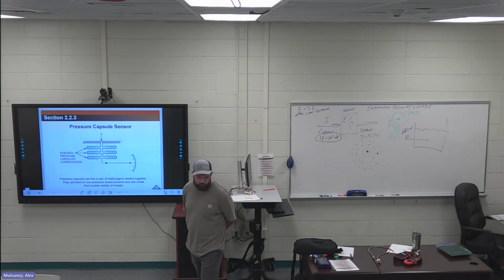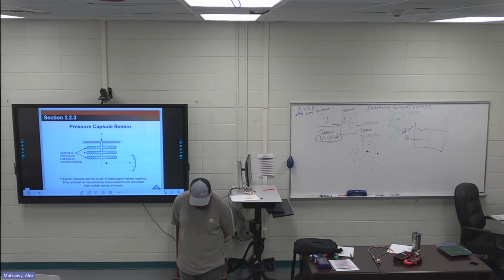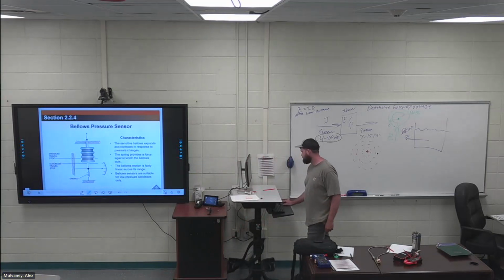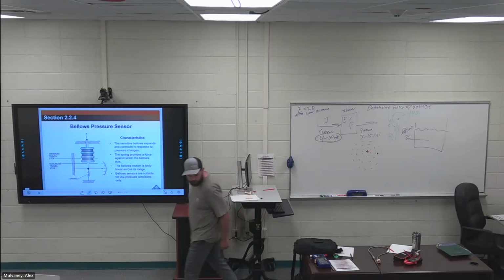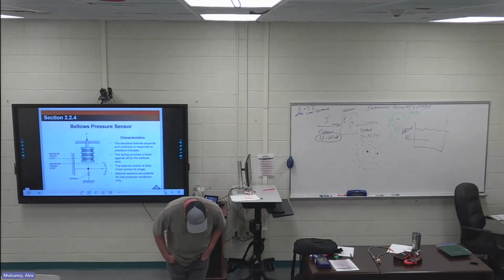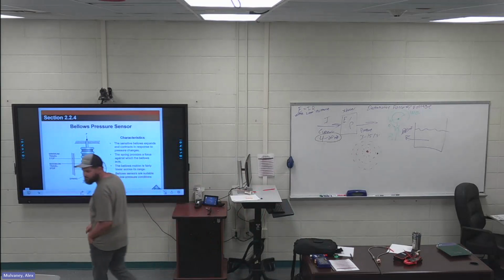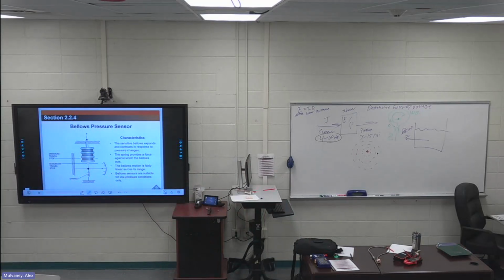Bellows pressure device, 224. Second paragraph, first sentence. The bellows type pressure gauge is usually built as a one-piece, collapsible, seamless metallic unit with deep folds formed with very thin-walled tubing. And the last sentence on the page is also highlighted. In practice, the bellows is always opposed by a spring, and the deflection characteristics of the unit are a net result of the bellows and the spring.